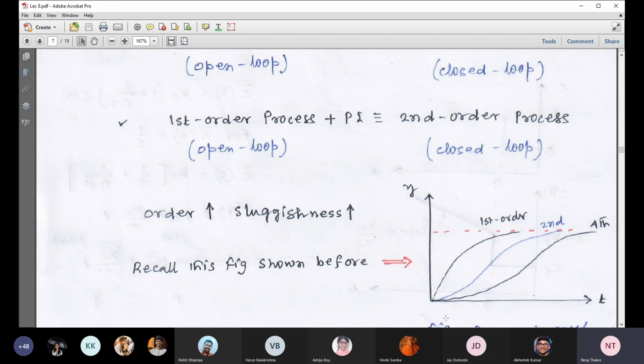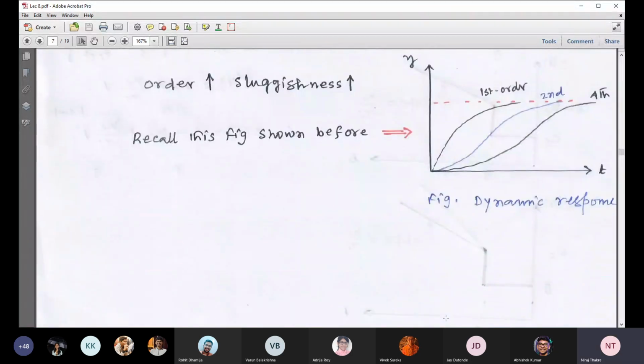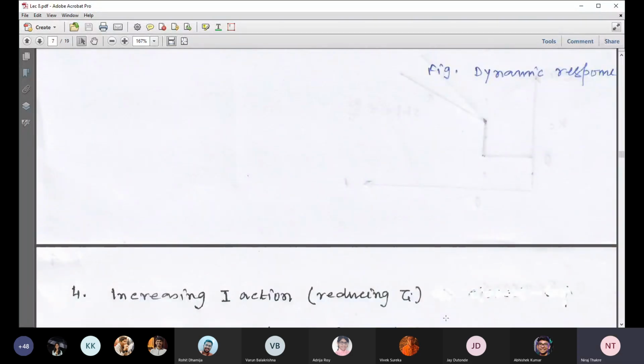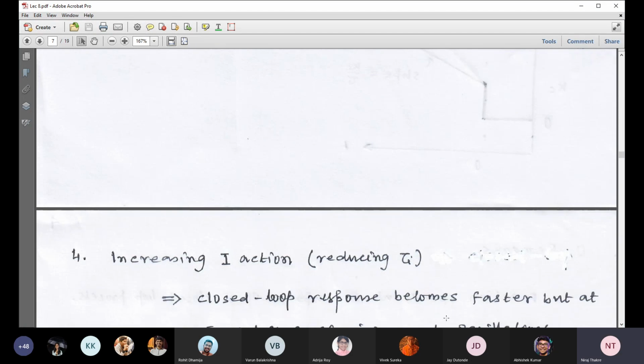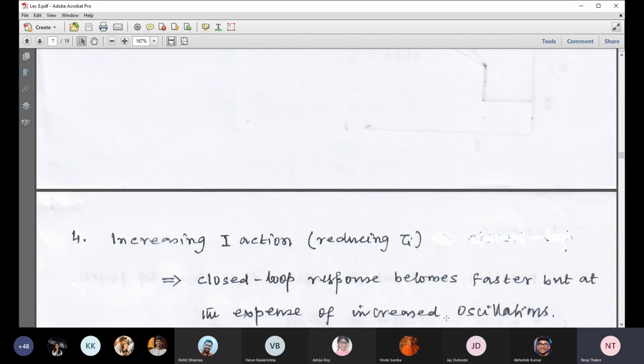Okay. So you remember this point, proportional controller speeds up the response. Integral action eliminates the offset. That's why we are very eager to include integral action with P. But as soon as we include the integral action with P, our overall response becomes sluggish. Fine. Now come to this point. The similar response we have observed for proportional action as well.